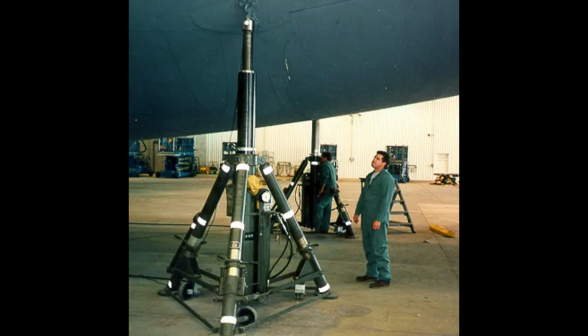When using two wing jacks, take special care to raise them simultaneously, keeping the aircraft level so it does not slip off the jacks. As the jacks are raised, keep the safety collars screwed down against the jack cylinder to prevent the aircraft from tilting if one of the jacks should lose hydraulic pressure.